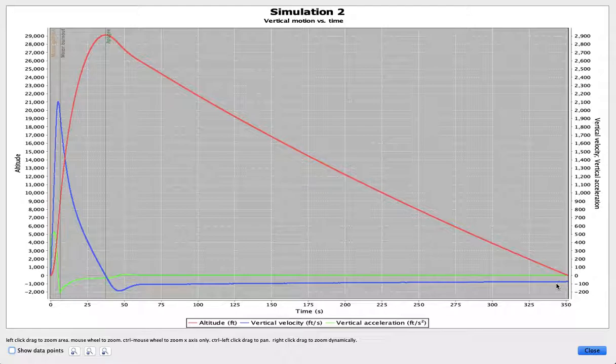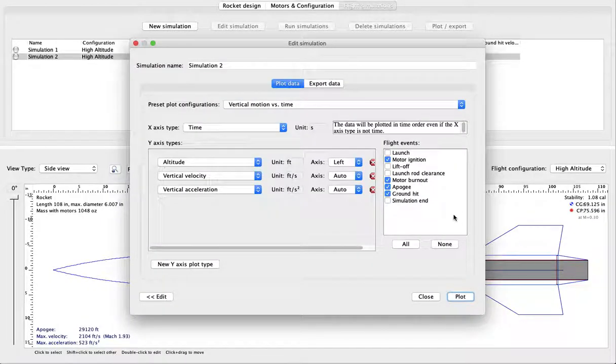Now it's important to know you want to hit the ground pretty softly. There's all sorts of rules of thumb, and they're pretty easy calculations for your parachute and how big it would be. But generally 20 feet per second and lower, you'd be fine.